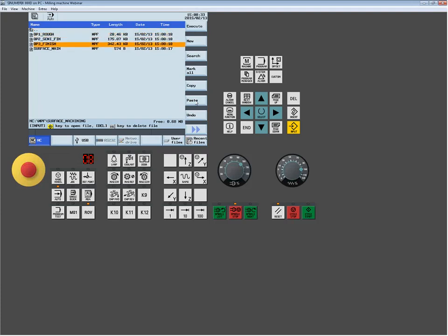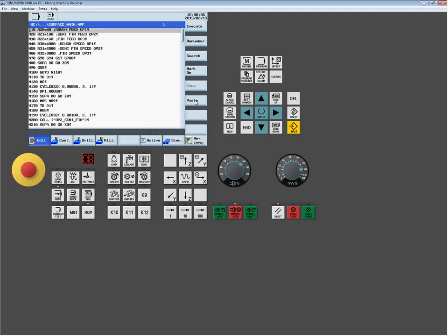So what does the surface program, or the main program, entail? Well, I'm going to do all my tool changes in here. I'm going to set up my high-speed technology statements here. I'm going to call up whatever the programs are from here. I'm going to do my safe retracts, my shutoffs, all that gets set up in the main. What I'm leaving the part program for, which now is a subprogram call, is simply my cutter path, allowing the CAM system to do what it does best, which is output cutter path.